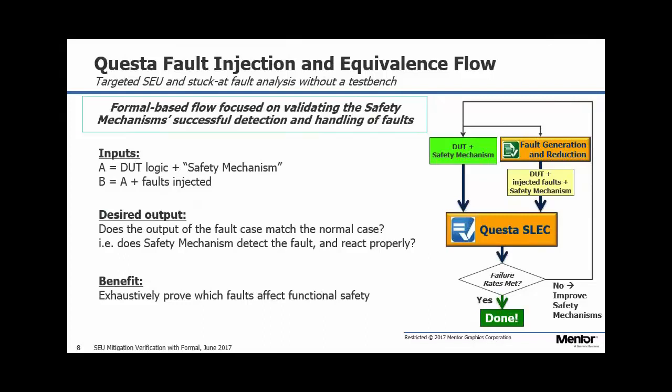Do you hierarchically go to the fault injection circuit and inject the faults? Let me think. Actually, what we do is we introduce a cut point. For formal, you can define a cut point, and we introduce a conditional cut point. So basically, the logic is modified hierarchically, but it's done through directives to the tools. The scripts will script this up, and it all happens automatically.